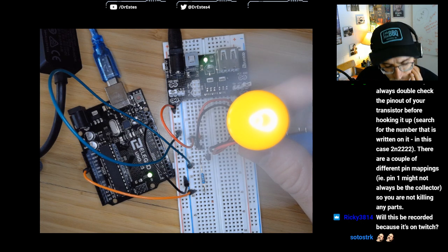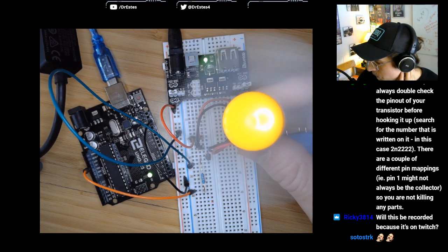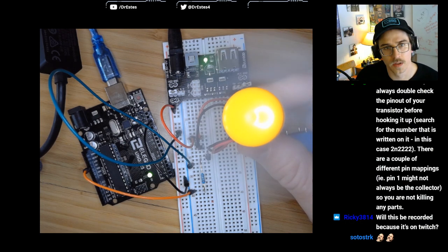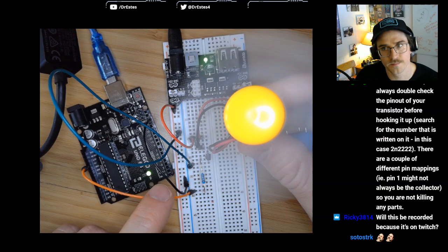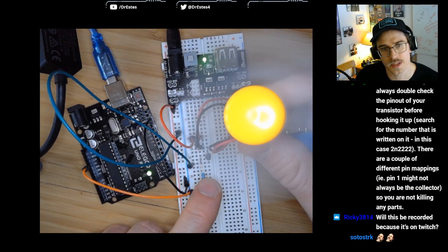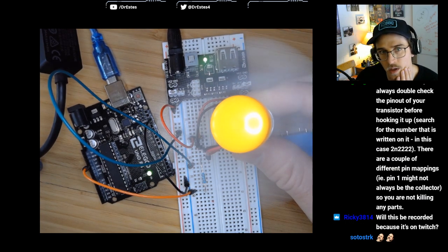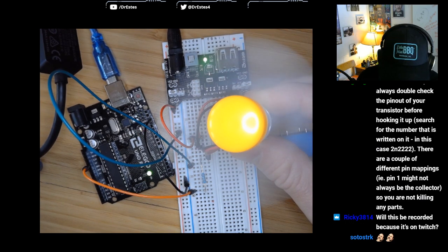But I think the default pin mode might be producing so little current that with this 5 kilo ohm resistor, maybe it doesn't have enough power to deliver the 1 milliamp that we need.